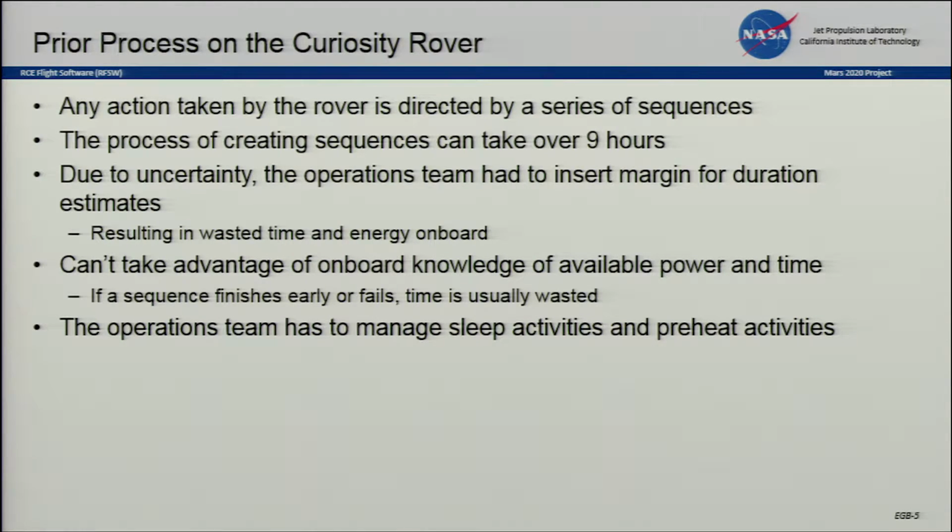Also, due to uncertainty in terms of how long a particular sequence might run, or just the onboard behavior, margin has to be inserted into these sequences, and that does result in some cases in wasted time and wasted onboard energy. Also, because the ground has to be in the loop for this sequencing, you really can't take advantage of the onboard knowledge.